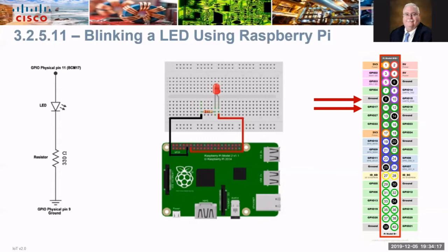The GPIO.BCM option means that you are referring to the pins by the Broadcom SoC channel number. Note the BCM pin number and the actual pin number are not the same. Double-check the pin-out guide for the correct pin number. Pin number 1 is located at the back of the board, opposite the USB ports and to the left.